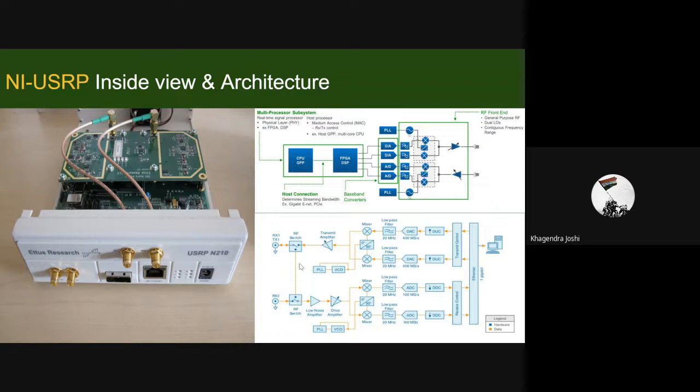So whenever something is being received, here you can see an RF switch. This is for the receiver, right? Whenever RX2 is being used, at that time the switch will be open here and closed there, so this port will work, right? At the input we have the RX input and a low noise amplifier. Only the TX signal will go through this. Whenever it is receiving, it will come from this particular channel. When RX is working, this channel. When RX2 is working, it will be connected and this will be disconnected, and this particular point will work.